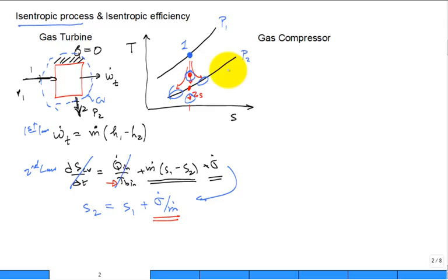Yes, isentropic. Whenever you see isentropic in this type of class, it basically comes because it's reversible and adiabatic. Now, isentropic only truly means entropy is constant. Couldn't I have some irreversibilities that want to generate some entropy while some heat transfer cools it to take it away and then still have isentropic? Yeah, theoretically, but there are no problems like that I know of analyzed in this class, in this textbook. Does that make sense? So when you see isentropic, it's basically reversible and adiabatic. Does it always have to be that? No.